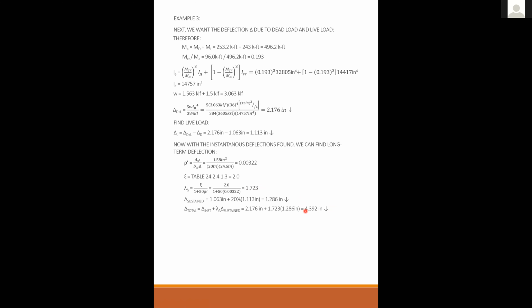Change the PSI of the concrete. Yes. And so what that would do is change that number right there. If you change the PSI of the concrete, it changes the modulus of the concrete. But that's not going to get you all that far, because remember, the modulus of elasticity for concrete is a function of the square root of the strength of the concrete. So doubling the strength of the concrete only gives you like 40% more stiffness. But yes, you could do that.